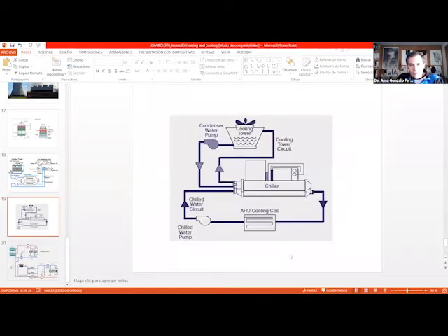Here we have exactly the same thing. We have the chiller. Here we don't see the evaporator and the condenser or the expansion valve or the compressor, but everything's here in that chiller. But we have this pipe going to the cooling tower with hot water. Then we release the heat, we cool down the water, and then we go down. And then from this element, we go to the cooling coil, and then we recirculate this here. Okay, we always need 4 pipes.